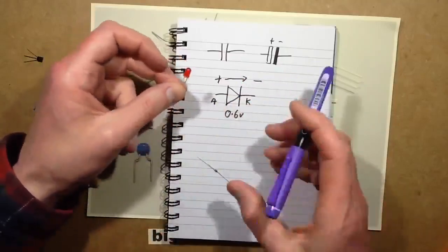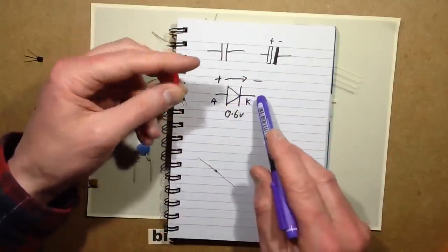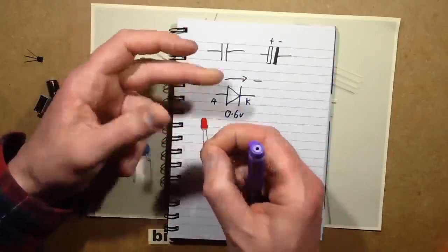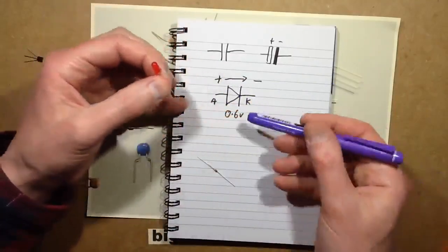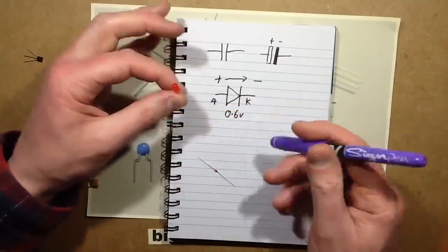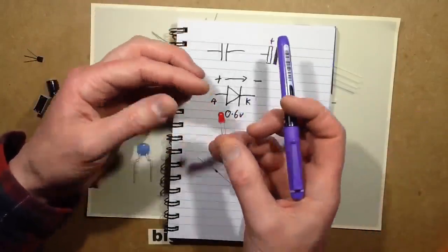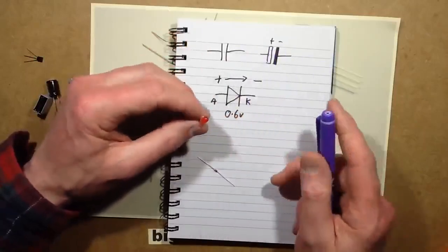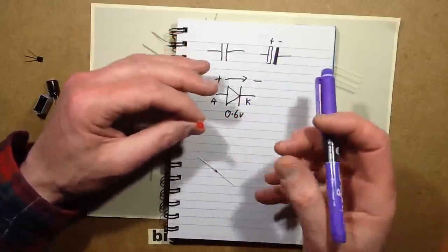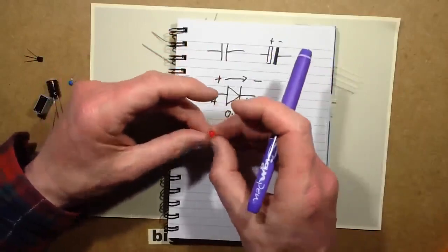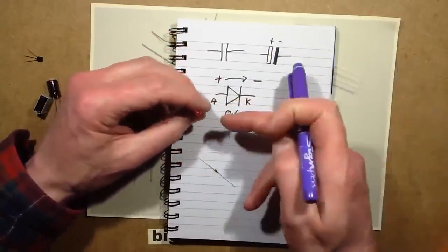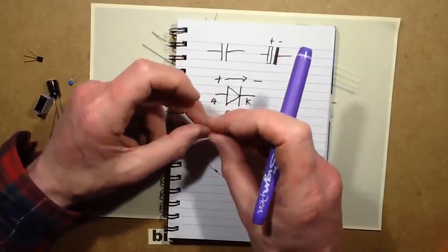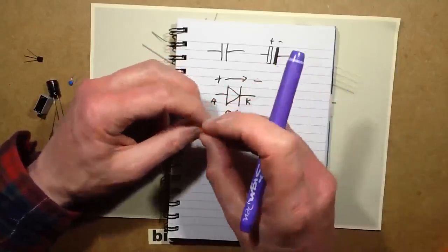But one of the things you have to note with an LED is, because they're optimized for emitting light, they don't have a high reverse blocking voltage. It's usually just about 5 volts. So if you were to connect the polarity wrong and exceed about 5 volts, in the case of white, blue, green LEDs, it may damage them, but with red ones, they may end up just conducting in the wrong direction, but not lighting, and not suffer damage.